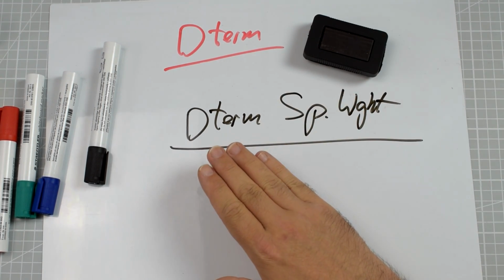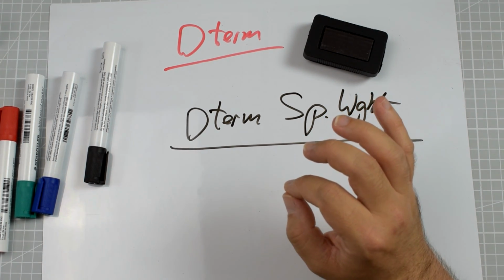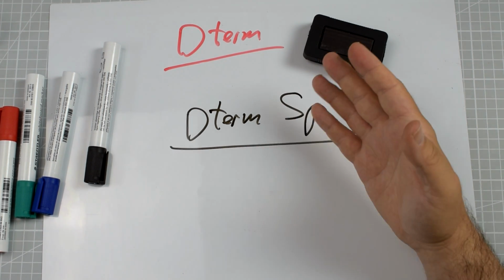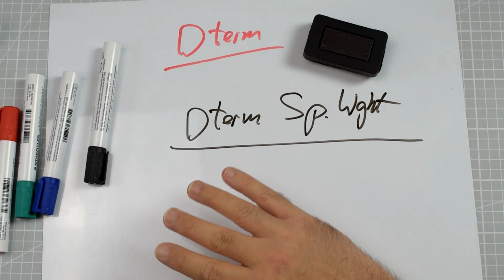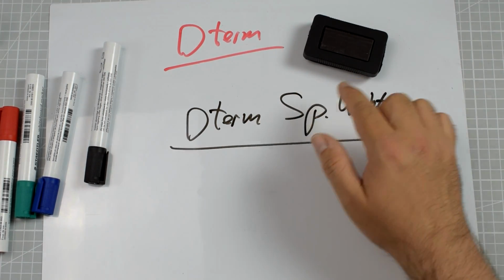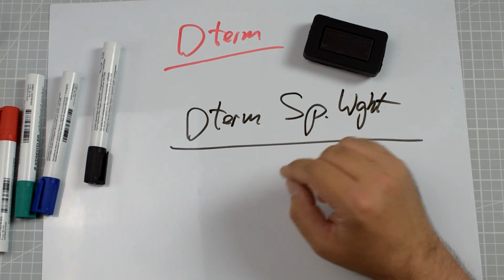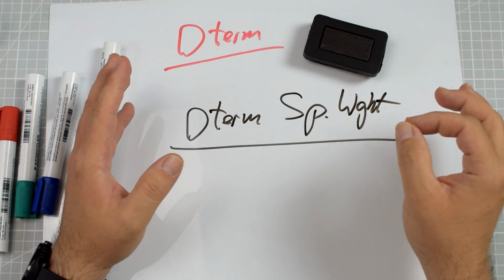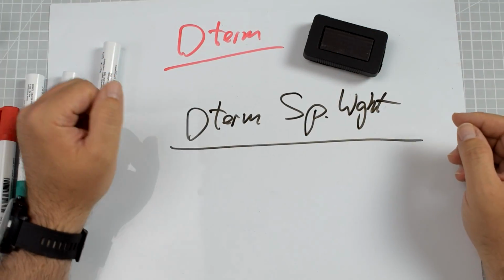But the problem was that it was extremely hard to tune the D-term, extremely hard to fight the derivative kick and to tune it to have a nice feeling. This is why currently Betaflight, for almost 2 years now, is using this D-term plus derivative feed forward, which is not really a feed forward approach. And from INAV 2.6, the next release of INAV will also have the D-term separately and the derivative of the setpoint, the control derivative, computed separately to have the best of both approaches.